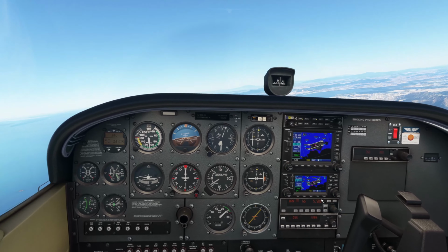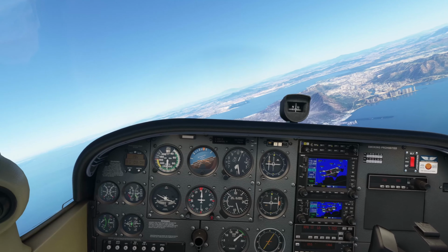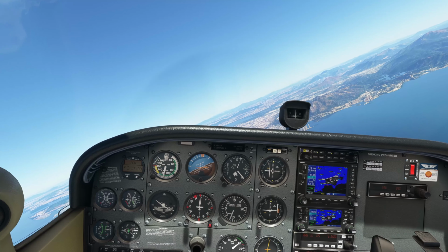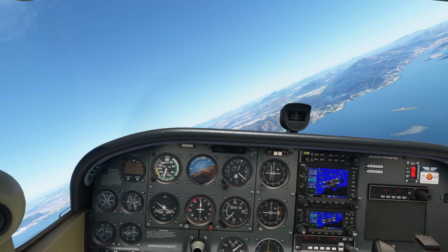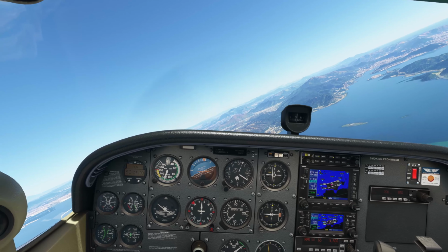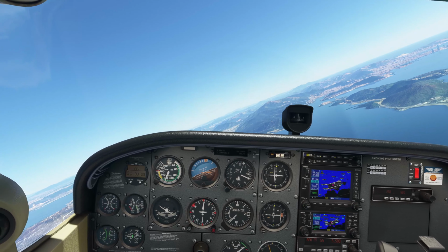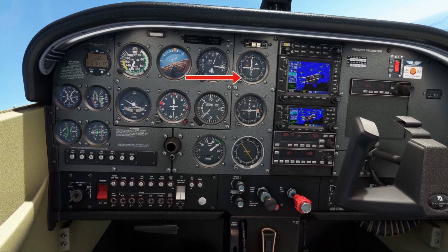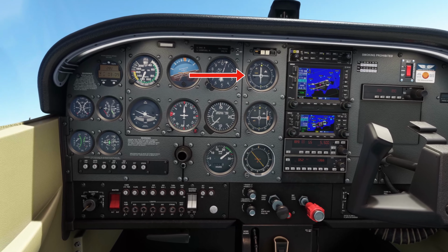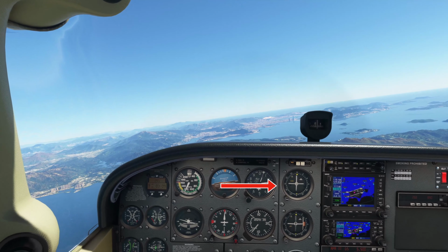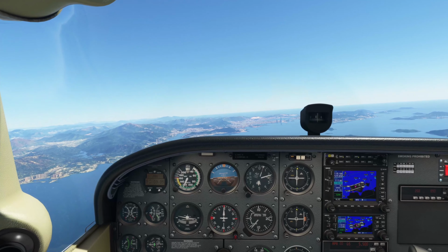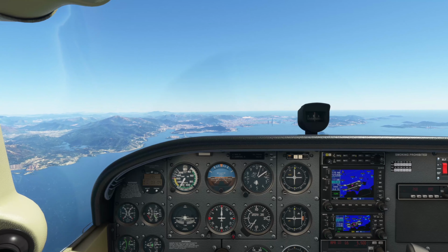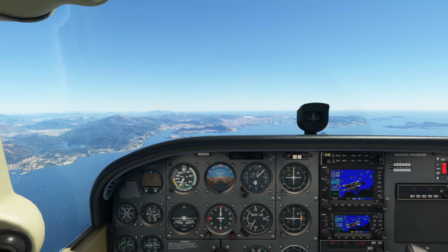Okay, excellent. The APR and GS values are set in the autopilot. We have engaged the localizer for direction and the glide slope for height, and the Skyhawk automatically turns onto the new course. You can also see the vertical needle now moving as the aircraft follows the beam from the ILS. Both needles are now in the centre circle. We are now fixed onto the ILS approach into Kai Tak Airport.